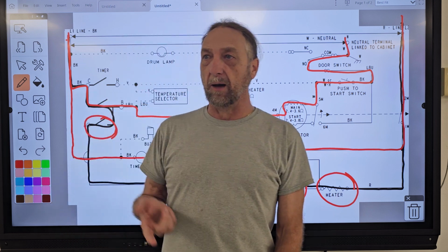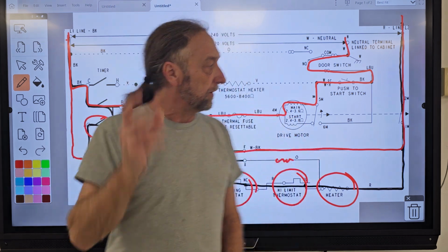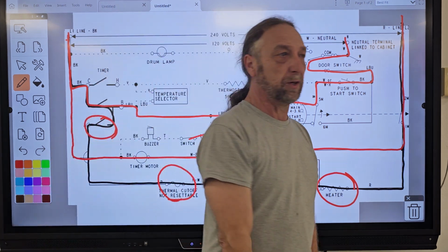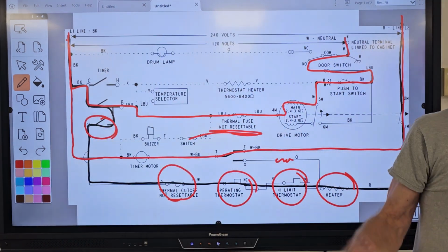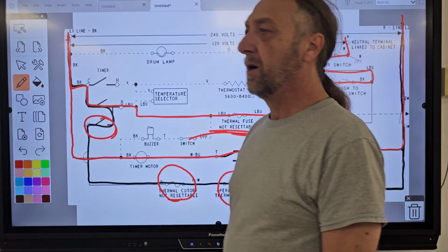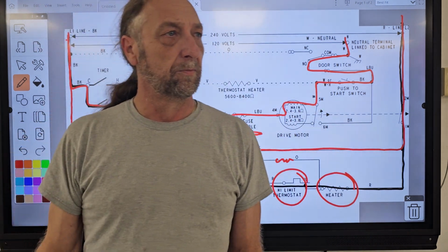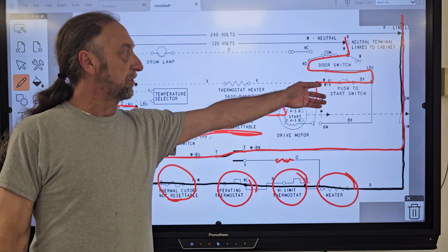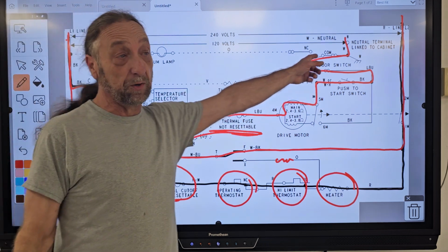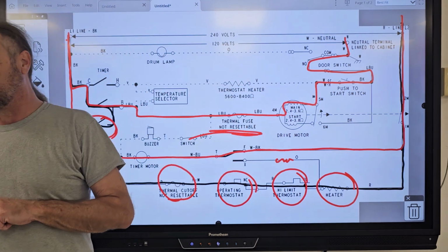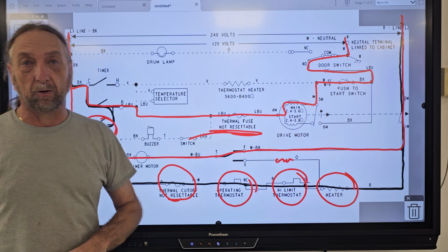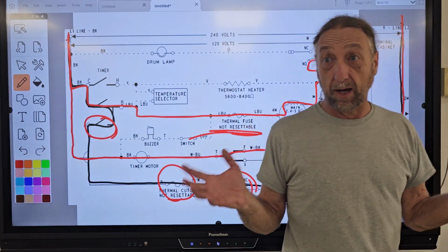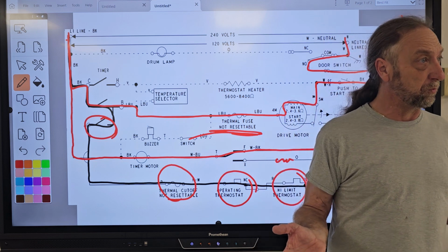If you do that in a competition, listen, this thermal fuse here, you talk to any technician with experience, they say, oh yeah, customer calls, said Whirlpool dryer won't start. It's either one of two things if it's not a power problem. It's either the door switch is bad, or the thermal fuse is bad. And nine out of ten times that thermal fuse is what's failed. I don't know how many of those thermal fuses I've changed, but the thermal fuse is why the motor's not